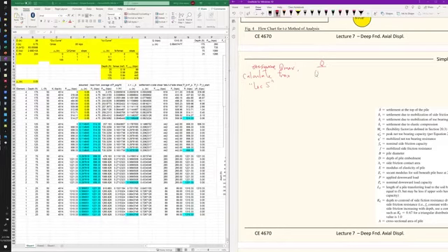Then after that, you need to have those: the QZ curve ready, and also the TZ curve. So this is the toe bearing displacement curve and the side friction displacement curve. Those are normalized curves. That's why you need to have the Q max and F max, because you have these ratios multiplied by the Q max for your piles, and then everything goes back to the loading for your piles. So likewise, you also need to have the TZ curve.